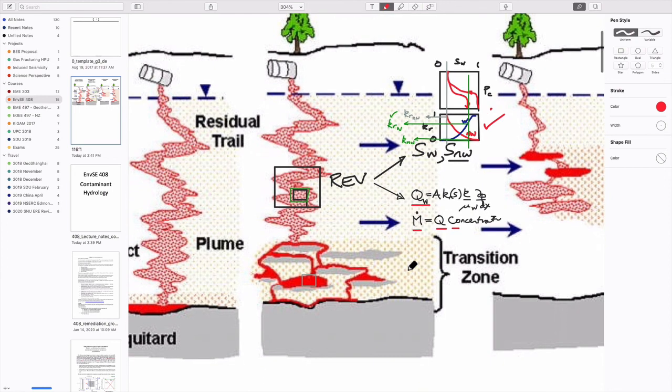And so we started off in week 1 saying that we'll look at the first couple of months where you drop this stuff into the subsurface. It does what it does in going where it goes. It's controlled really by interfacial tension in where it goes. That's the big force that controls behavior.